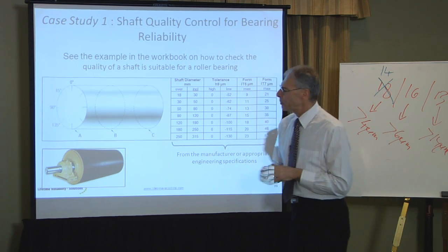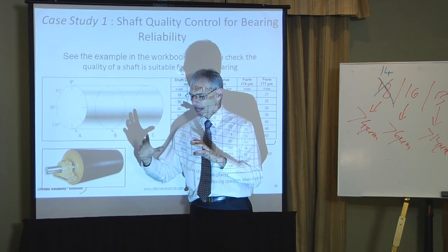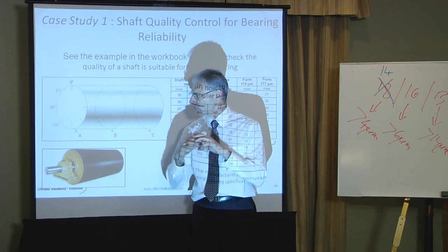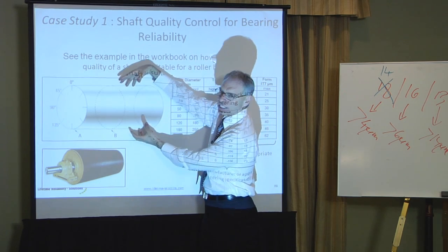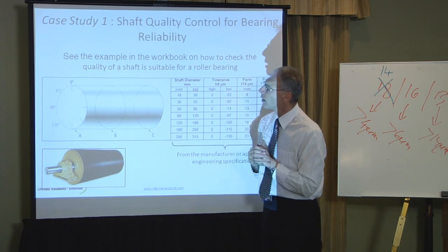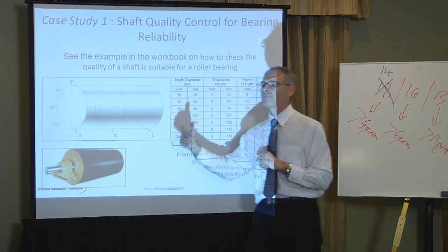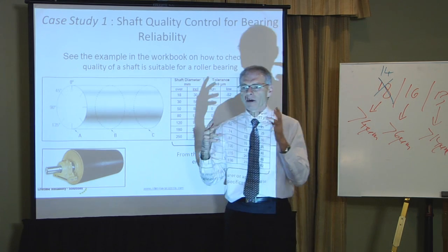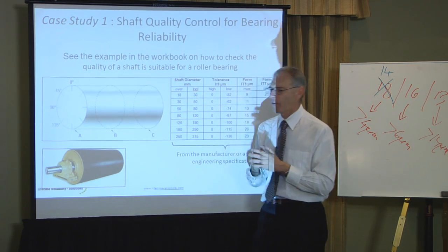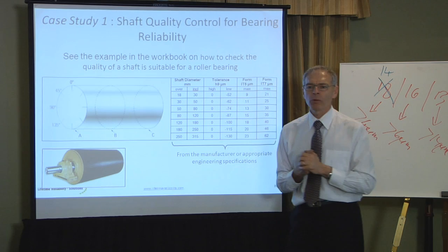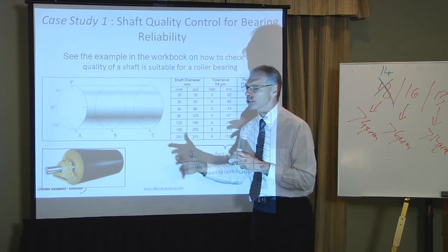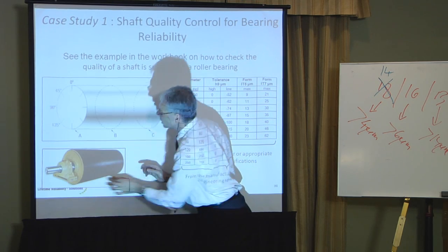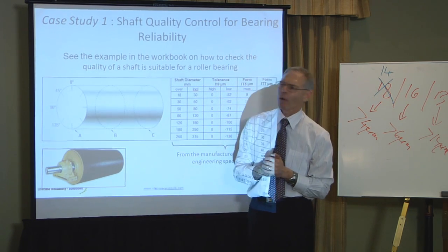Now, this particular bearing was on a tapered sleeve, and it was a spherical roller bearing, quite a large one, 6 inch. This shaft's actually a 6 inch shaft, 150mm shaft. This company eventually called in the bearing manufacturer and said, look, this is costing us an absolute fortune. We don't know what's going on. Can you please investigate? The first thing the bearing manufacturer said, micrometer the shaft. Go out there, next time it fails, take measurements of the shaft, where the bearing sits, not the whole shaft, just where the bearing sits, and here's what they asked them to do.